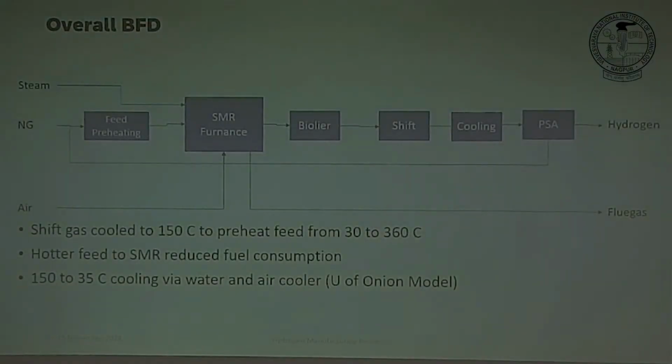But there is an optimum temperature approach, the temperature difference between hot stream and cold stream. So in this case, it's somewhere around 60 degrees. So we can heat the stream up to 360 degrees because our product gas is at 420 degrees here, right?